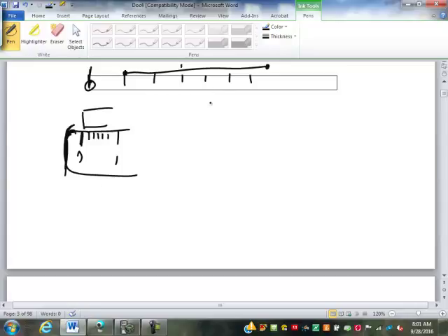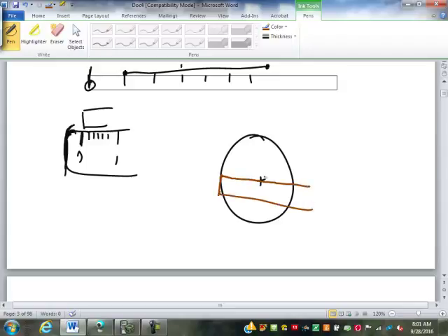But what now if I wanted to measure a circle? Well, the easiest way is if I'm showing the center of the circle, then I'm just going to take a ruler and I'm going to put the zero end on one side and run the edge of the ruler that I'm reading the measurement off of so that it goes through the center. Then whatever's over here, that's the diameter of the circle. You got to be really careful.